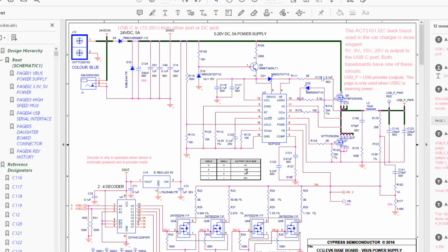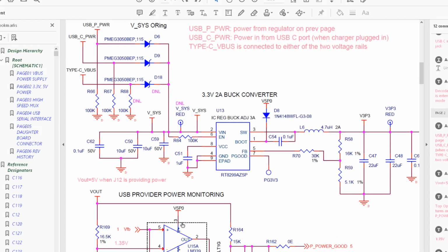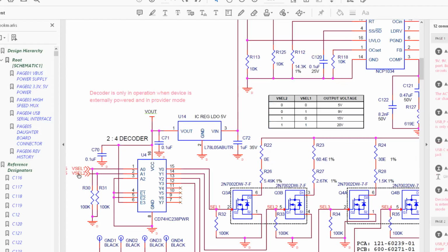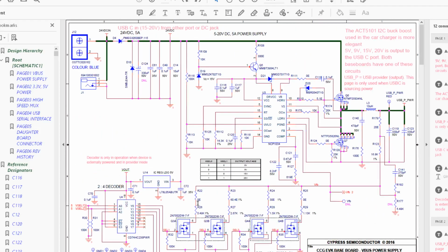And the way they're doing this is by putting in a 2-wire decoder, so either 00, 01, 10, or 11, and based on that you get 4 outputs. Depending on what you choose here, you'll get a different voltage divider circuit on your feedback loop. For example, you get 5.49 on the feedback loop, and the positive side of the feedback loop is always the same.